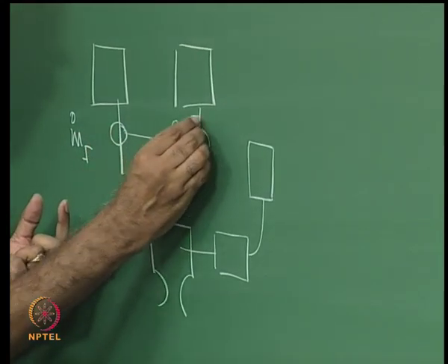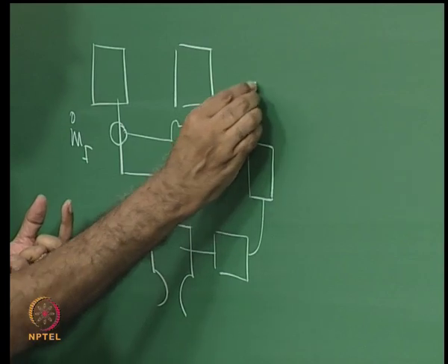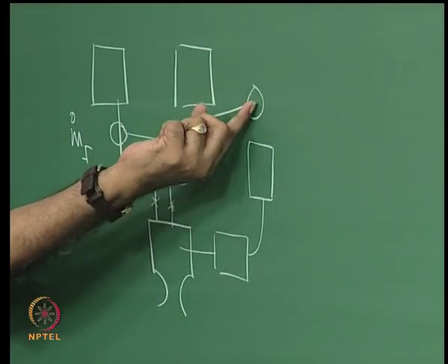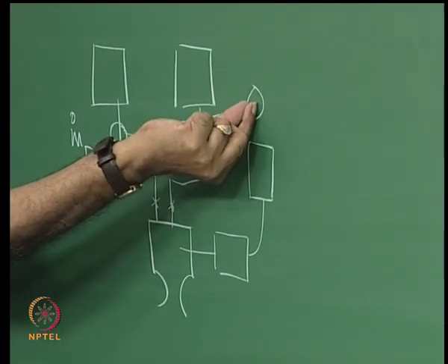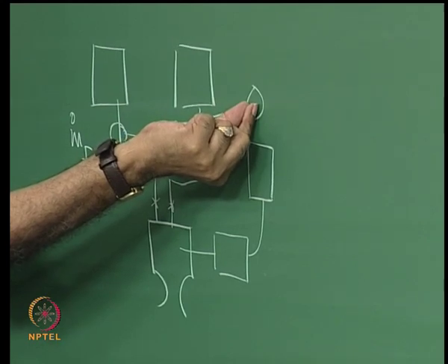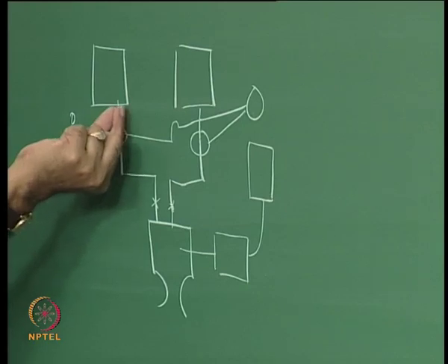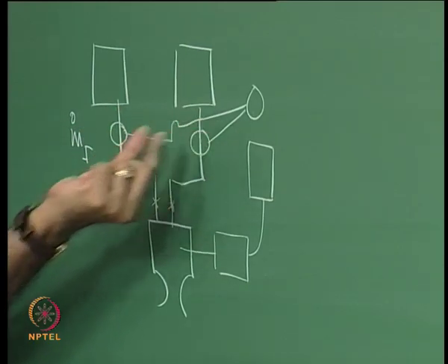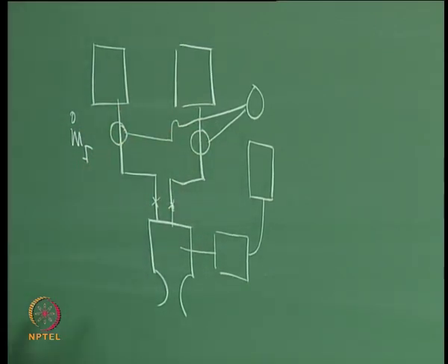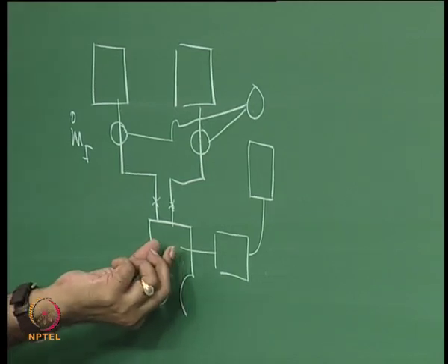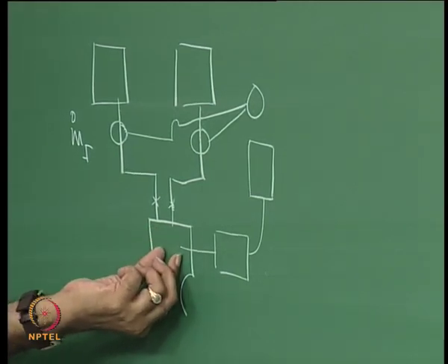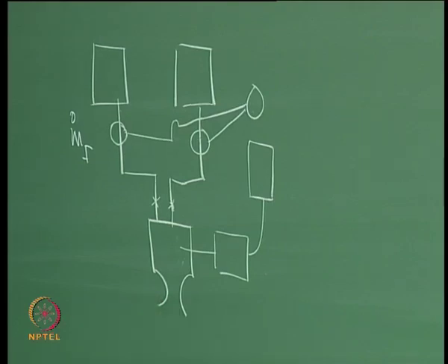Let us say I feed this signal over here, I feed this signal over here through a mechanism here, and if I find that the mixture ratio is exceeding, I can give a command to these valves or to a valve upstream to slow down and all that. A control is possible, not only starting and stopping, but also mixture ratio control, maybe pressure control, and hence the thrust control. Therefore, we say a liquid propellant rocket is more versatile.